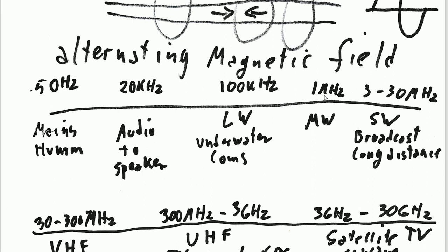Then we've got 1 megahertz. 1 megahertz is smack bang in the middle of the AM band, also called medium wave. In Europe, it's pretty much discontinued. In America, it's pretty much alive. It goes from about 540 kilohertz to 1.6 point something megahertz. And again, at daytime, it follows a little bit the curvature of the Earth, so you get over the horizon communication.